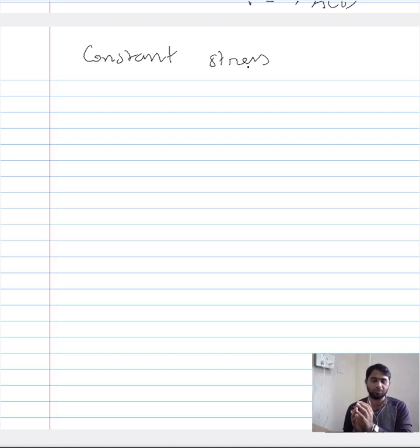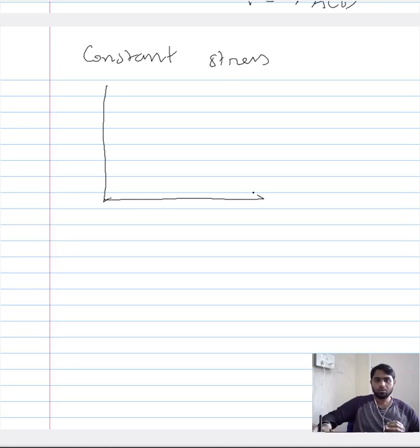So there is a name for it. You could make some effort to find it, or some of you might already know. If you choose such a condition wherein the stress, characterized by the area at a given instant, is constant, then you have an ideal 2-dimensional plot with the creep strain on the y-axis and the time on the x-axis.